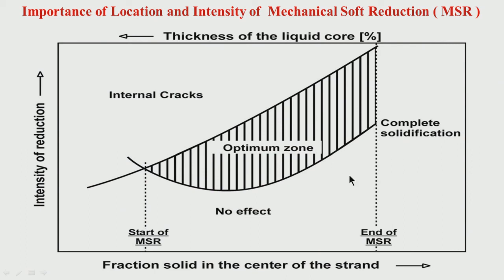So again I am repeating, depending on the type of solidification characteristics, you may have different types of defects, whether surface or internal. Even in internal you can have them at the center or at other locations. If you understand the solidification sequence, then you can understand why those cracks are forming and why quality is getting affected. And if you understand that, you can devise the solution, the way which can take care of this problem. This is very important for understanding. Thank you very much.